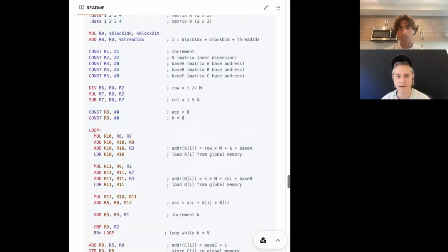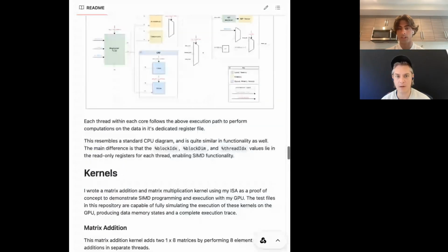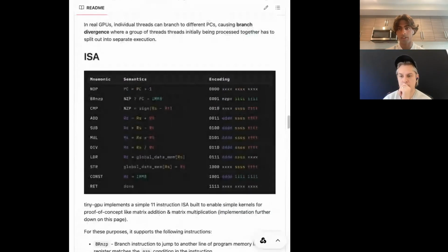So there's a couple of connections in the instruction set to the hardware. There's 2 important connections, and they're very much demonstrating that this is a dummy project. So first of all, if you look at the instruction set, each instruction is 16 bits, which means that the first 4 bits are the opcode, meaning that since there can only be 16 different combinations of that, with this design I've created, there's actually only space for 16 total instructions, which means there's only space for 4 or 5 more instructions if I wanted to add them.